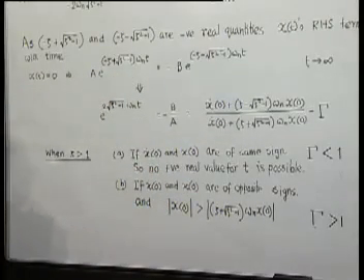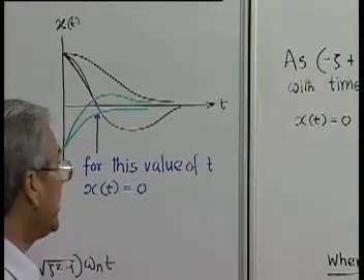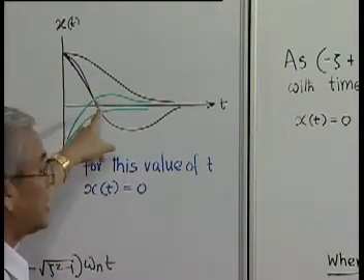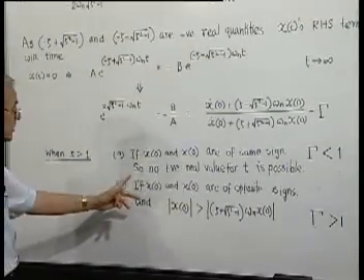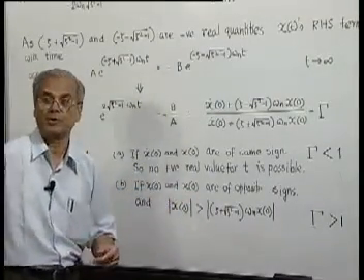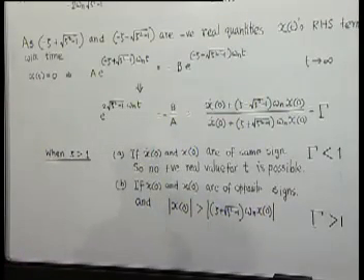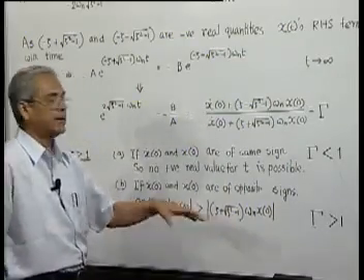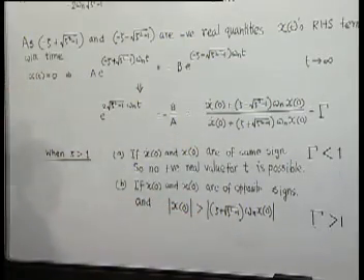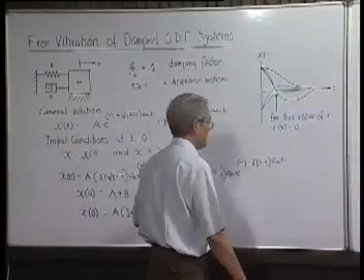So for the overdamped situation, the motion will always be aperiodic, and the possibility is that it may cross the equilibrium position only once, and that too only if the initial velocity and initial position are of opposite sign, and the initial velocity is of enough magnitude to be more than this quantity. That is when it is possible for the mass block to cross the equilibrium position.